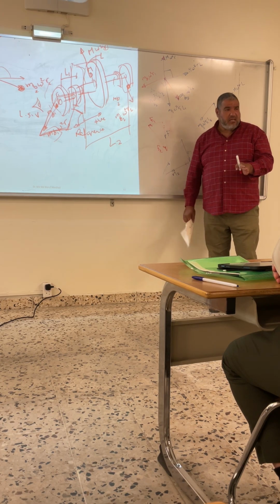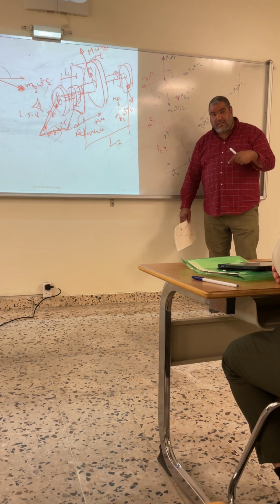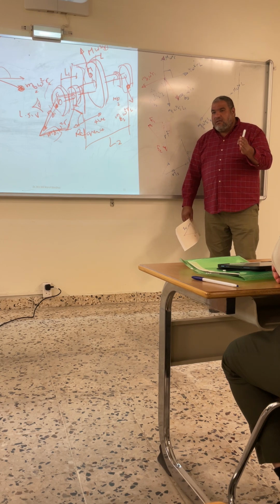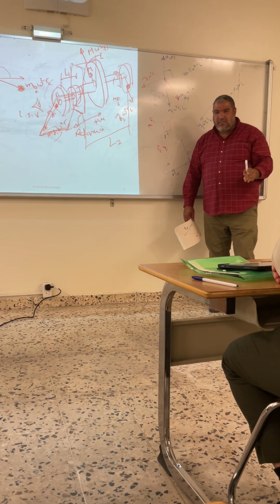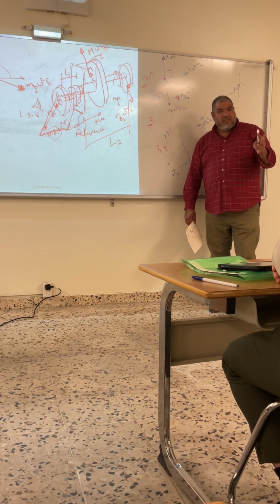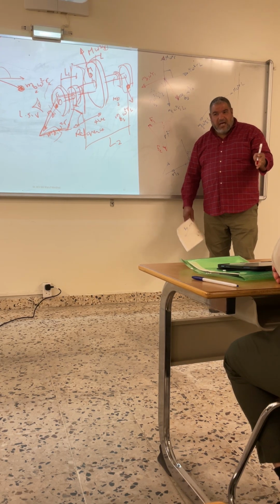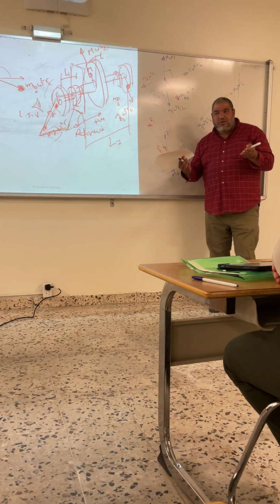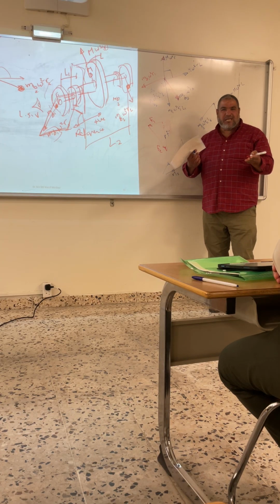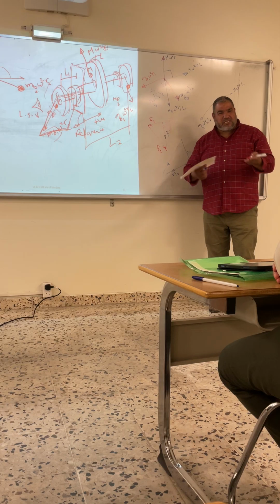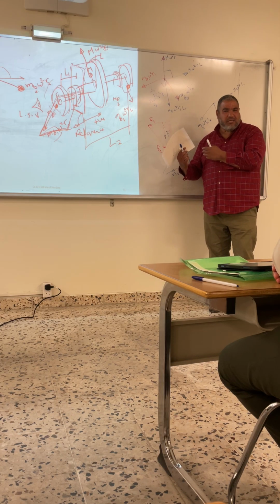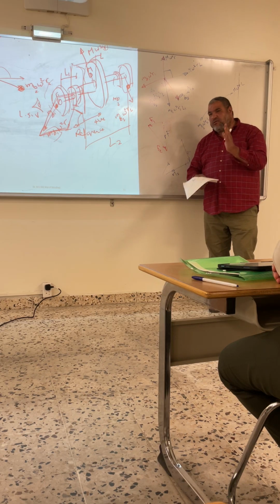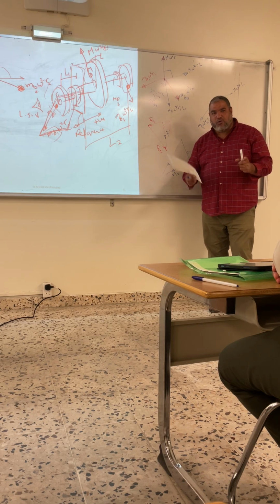I'm not going to represent it right now, but I'm just trying to refresh your memory with what we did last time. We ended up having a column which is M times R times cosine theta, and you sum up all these values, and the other column is M R sine theta, and then you end up with two equations. One of them has cosine and the other one sine, so you take the summation of the squares, and you end up having cosine square plus sine square. You haven't forgotten what we did last week, guys. And then you end up having one, you get rid of the theta, and you should be able to get the MR product.